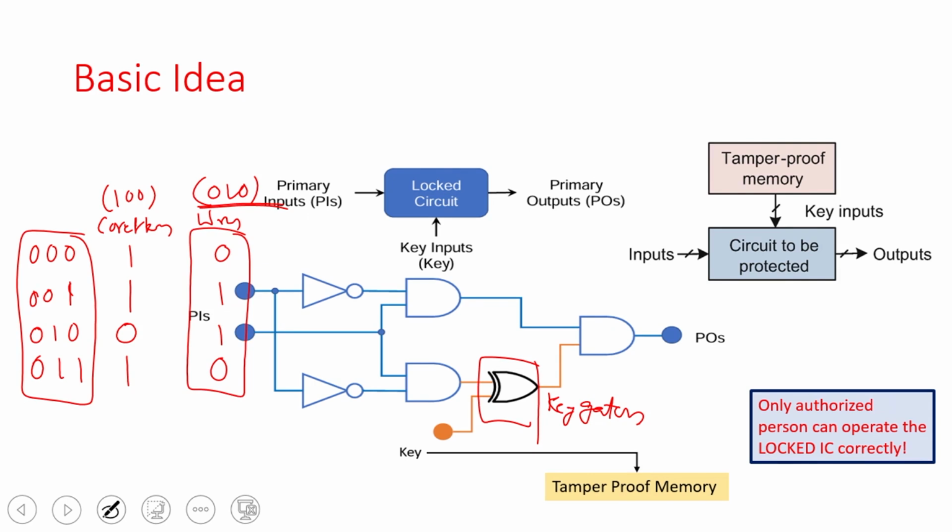At the manufacturing level, I do not need to check the functionality. I have to just check whether there is some stuck fault, some bridging fault and all those things, right. So that the desired output is coming or not. I do not need to check the functional correctness, I just want to check the structural correctness or manufacturing defects. If there is a stuck at 0 here, you will not get 0 at the output, because it is stuck here, right, to 0. So, those kinds of faults, the stuck at 0, stuck at 1, can be detected with a wrong key with this combination of values, right. This is my golden input output.